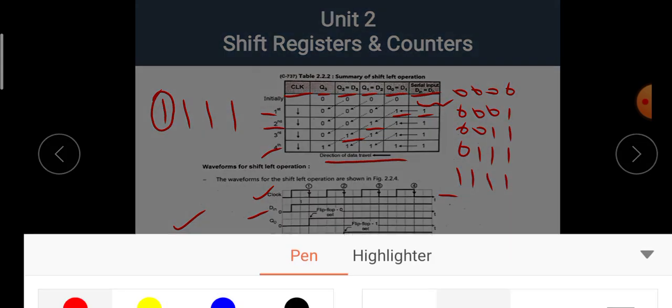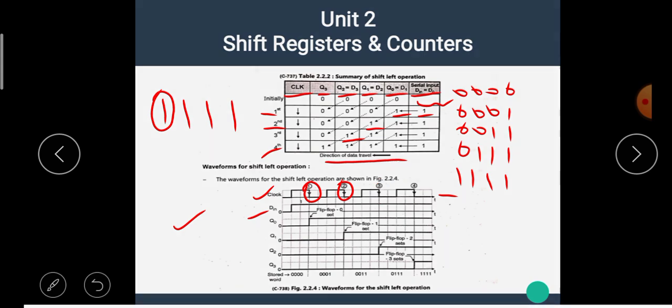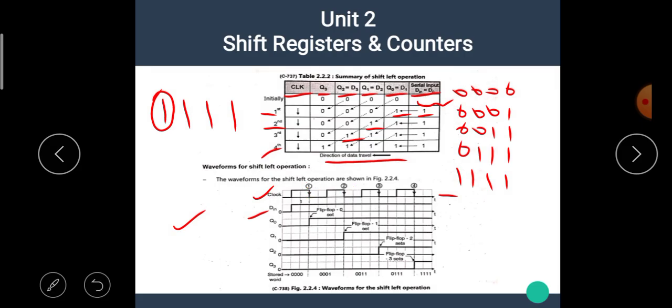1111. Okay, now our shift register responds only to the negative edge of the clock, hence only at these positions the output of the shift register is changed. Now let's see the first arrival of the negative edge. When the first negative edge occurs, at this time data in is 1. Here only Q0 sets, hence at this time Q0 becomes 1.